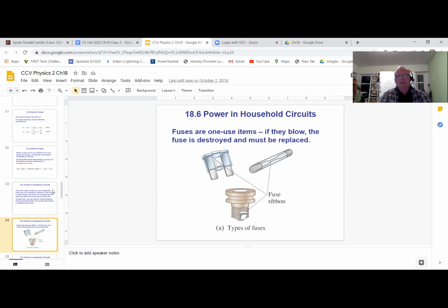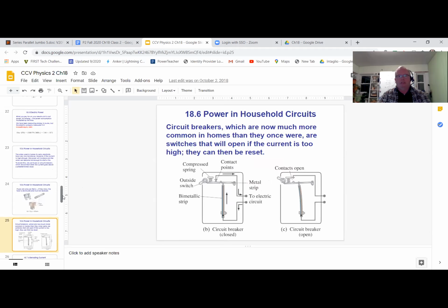So it is relatively common to blow a fuse in a car. Now, in a house, blowing a fuse is not that great. Sometimes some of the really old camps still have fuses. And that means that you have to have spare fuses around if you're going to fix it. But you don't want to just throw the new fuse in without figuring out what the heck caused it.